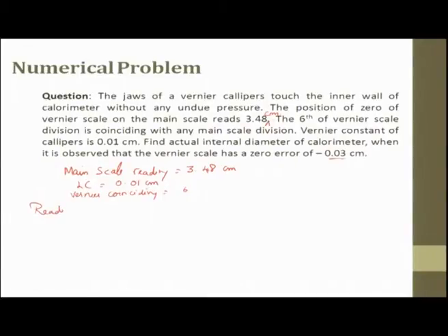Now, the reading is nothing but the main scale reading, MSR, plus the vernier coinciding division into LC.